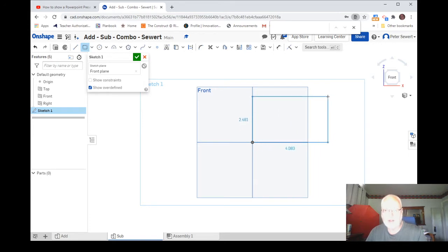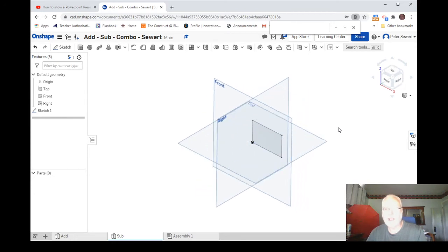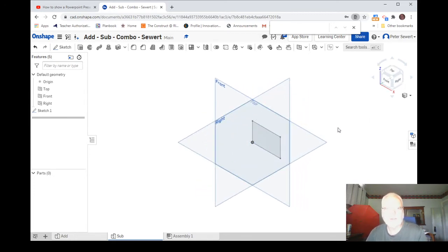I'm going to bring my cursor out and left click, and then in that small box at the bottom, I didn't move my cursor anywhere because if I do, those boxes will disappear. I'm going to put in 2.25, hit enter, and then for the height, I think it was 1.5. Yeah, it was. Now I have my rectangle there, and I'm going to close out my sketch. Just for variety here, I'm going to right click and say isometric. That's probably my favorite way of turning on isometrics.